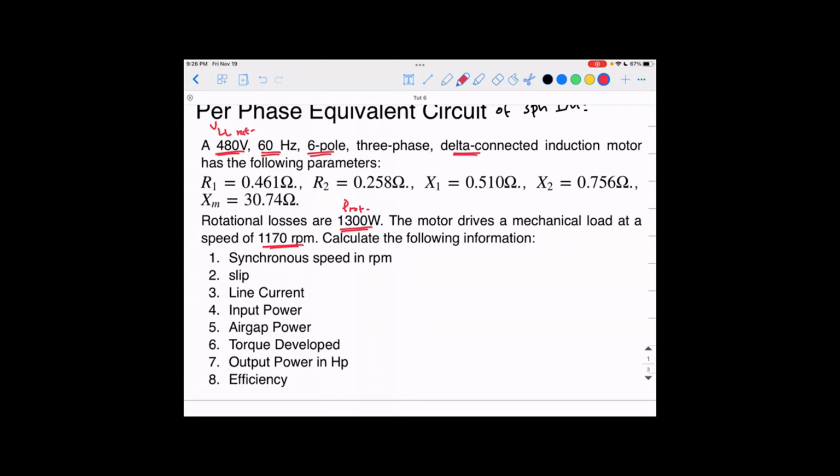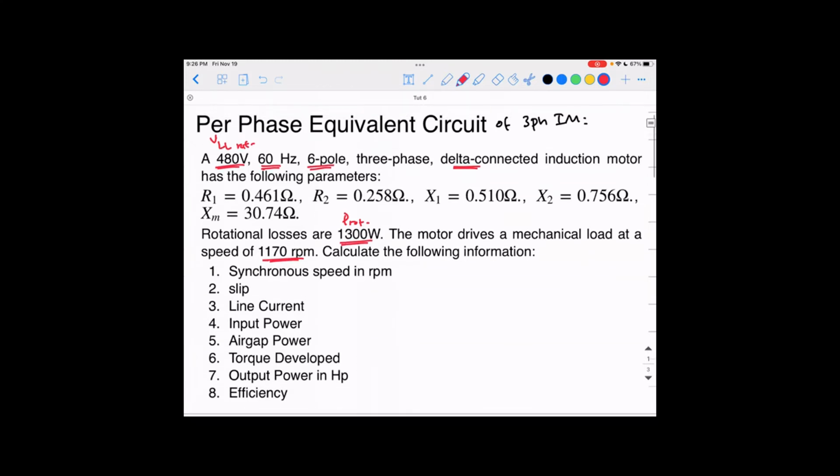And guys, you have to just have this in your mind. He has to specify a loading condition all the time. Otherwise, you will not be able to solve anything, because you are trying to calculate or estimate the performance of the machine when it's applying a certain load. So he has to give you some information to give you an idea about the load of the machine. He can give you the output power of the machine, or the torque developed by the machine, or the speed of the machine, because those all depend on the load.